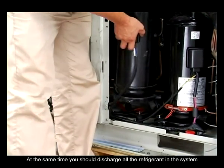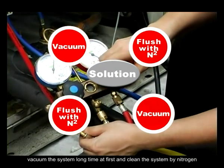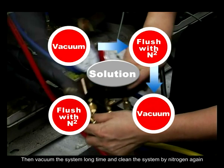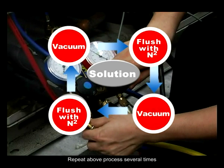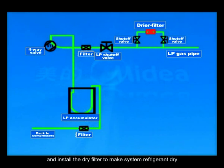At the same time, you should discharge all the refrigerant in the system. Vacuum the system a long time at first and clean the system with nitrogen. Then vacuum the system a long time and clean the system with nitrogen again. Repeat the above process several times. You can change all the refrigerant oil if necessary and install the dry filter to make the system refrigerant dry.